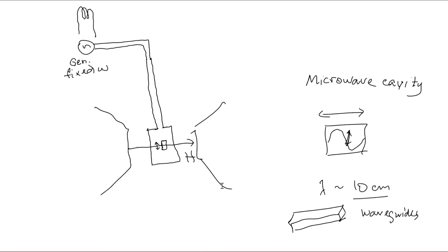When we fix the frequency, what it means is that we can choose the geometry of the waveguides for this particular frequency and particular wavelength, and we will send waves in there. So waves are going in there, and in this cavity they resonate. They force the magnetization, so I will draw the magnetization of our material below here. The magnetization would be pointing this way, and it would oscillate up and down. So this is capital M, this is small m. M will oscillate at our frequency omega.